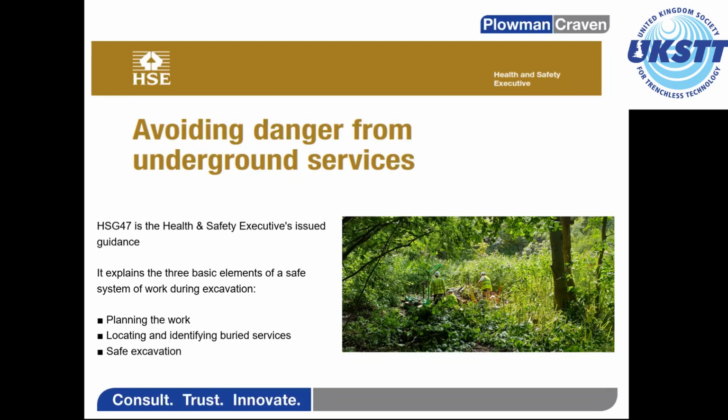Consider the risk to operatives when using specific types of equipment. Although there is more control with hand tools, there is much higher risk of injury to personnel. Each contributor should consider their own results and working areas, provide an opinion, and work to the requirements of HSG 47 and follow safe dig practices as a minimum to reduce these incidents. As an example, safe digging practices would be scanning the ground layer by layer throughout the excavation to ensure that there are no cables or ducts running below the site.